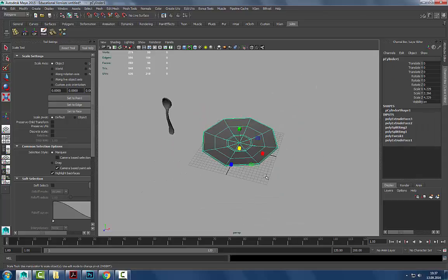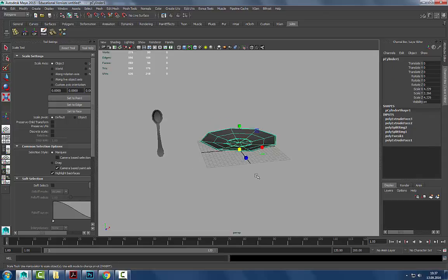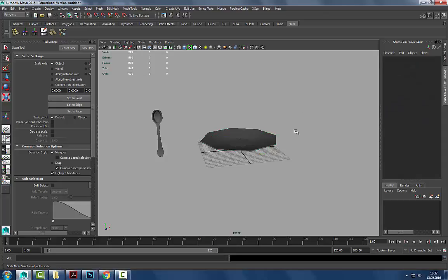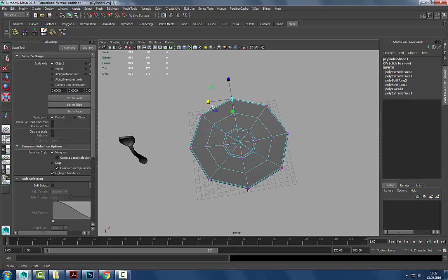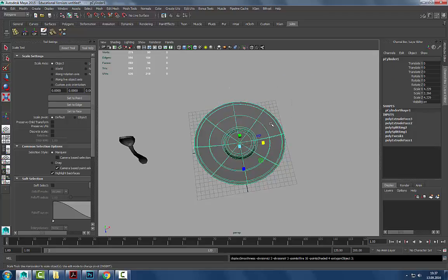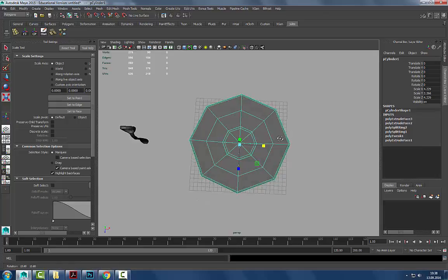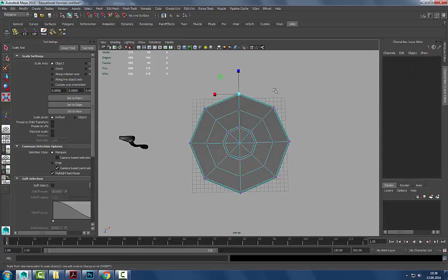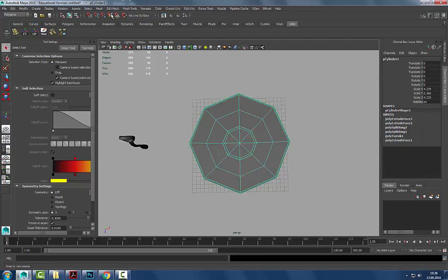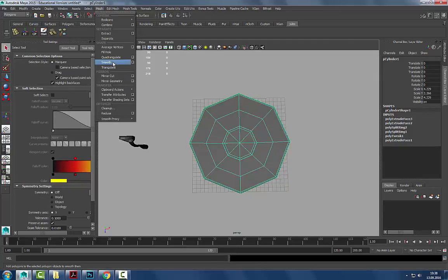So the difference between subdividing, so pressing 3, right? If you're creating, we were talking about this over the break, if you're delivering an asset for a final in-game asset, let's say, you probably want to stay clear of having it look this faceted on the edges, because this looks nice when we subdivide when we press number 3. So in Maya we can just subdivide and then hit render and fine. Typically, but we'll get back to this, because we don't really want to UV map a version that's this crude. So eventually you need to probably do a final smooth.